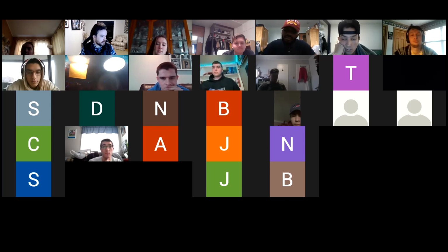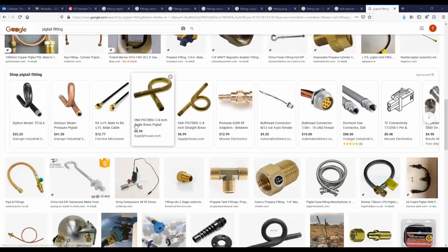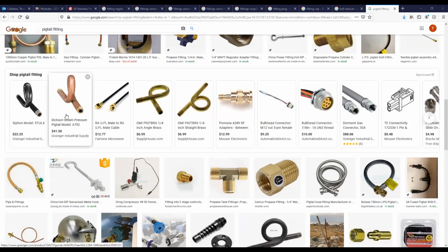The only thing I can see with this being utilized is, I'll pull up a picture so everyone can see. Everybody see? That's what you had, right? Yes. Okay. So the only thing I can see with that is room for expansion, on something like steam. It uses a steam boiler, so yeah. That's the only thing I can think of, that it just needs room for expansion, where it can expand in both directions on the piping.